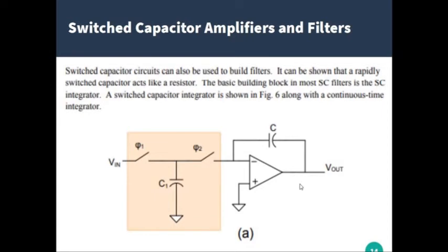Alright, next. Switch capacitor circuits can also be used to build filters. It can be shown that a rapidly switched capacitor acts like a resistor. The basic building block in most switch capacitor filters is the switch capacitor integrator. A switch capacitor integrator is shown in figure 6 along with the continuous time integrator.